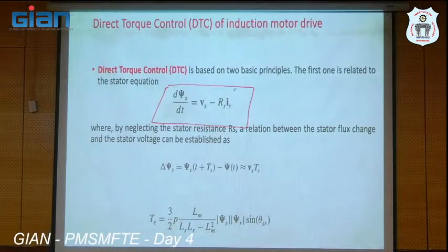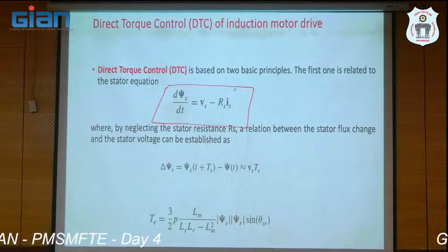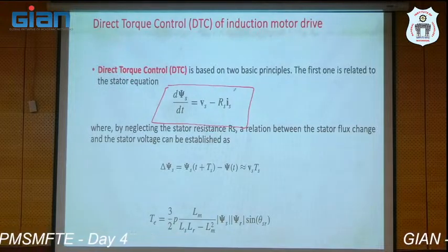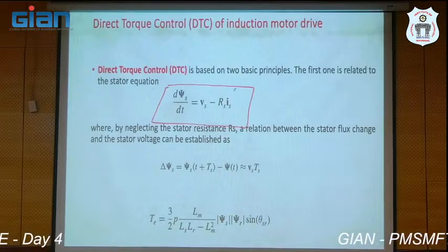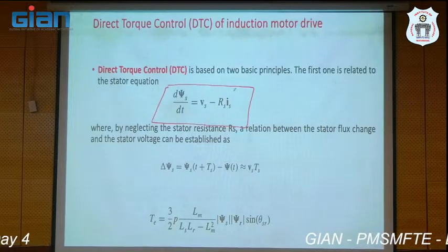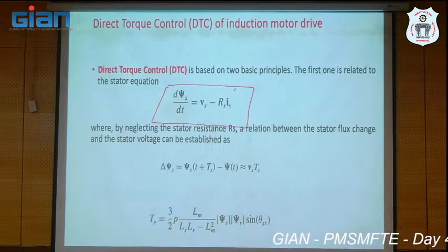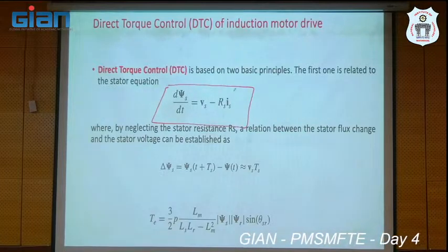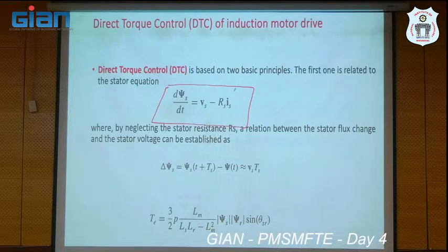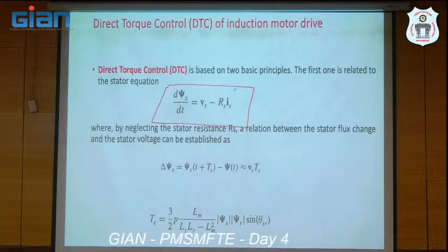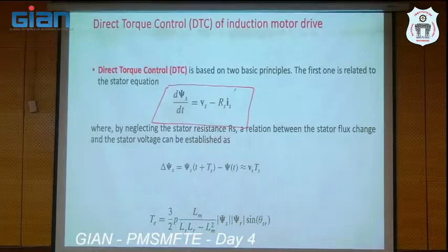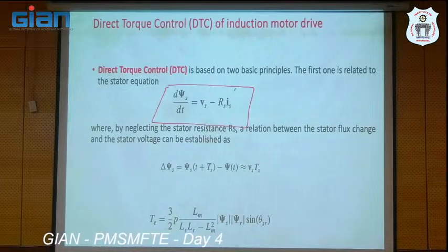In FOC, yesterday we controlled the resultant magnetizing flux as well as the resultant torque producing component. Iq's responsibility is to control the resultant torque producing current.